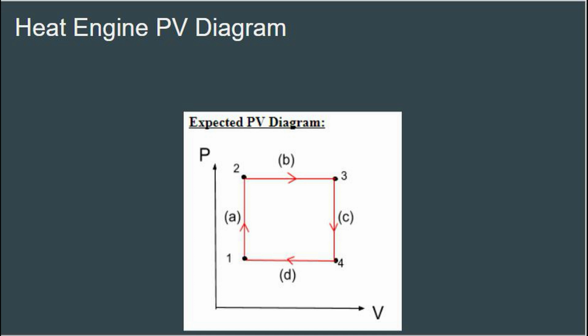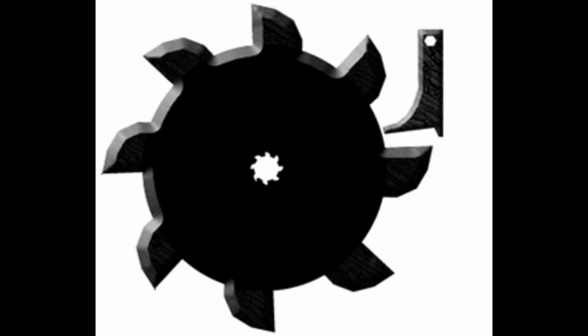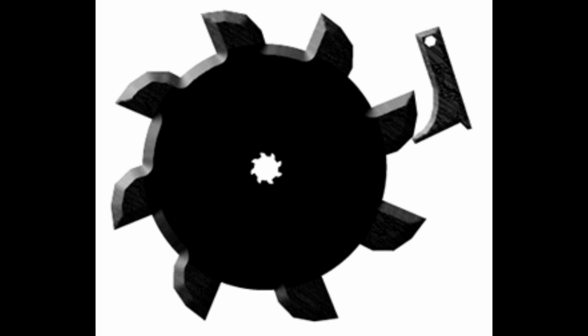The change from state 3 to state 4 is isochoric compression. Once the piston reaches V2, we move the cylinder back into the cold bath, which causes a significant enough temperature change to move the piston. The idea was that at this point, the weight is lifted off as the temperature increases. Also, as the temperature decreases, the pressure drops until it reaches its initial temperature. Before the piston moves down, our goal was for a ratchet to stop the wheel from rotating backwards with the piston. This way, we could hypothetically store potential energy from each cycle and add them.